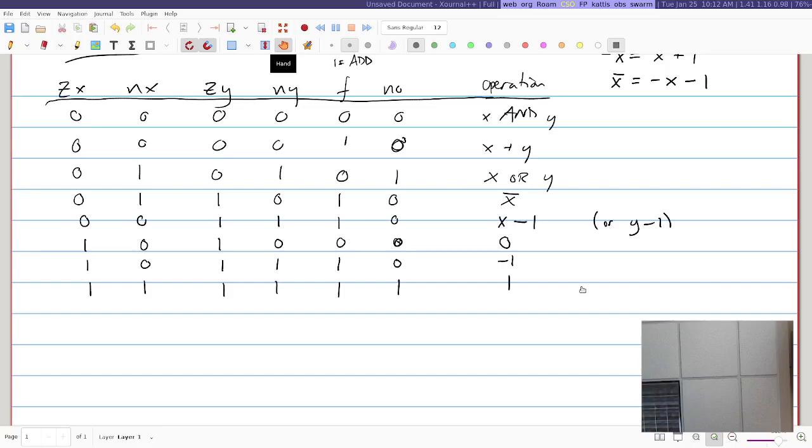Division is expensive. So if you were going to divide by 2, you'd rather not use the general division circuit, because dividing by 2 is just shifting the bits over. The computer also has a way to shift bits, and that's really fast. That would be something a compiler would do. It would notice, oh, you're dividing by 2 here, so I'm going to output the instruction that tells it to shift bits, not the division instruction. That can make a big difference, but for this ALU that we're talking about, there's no difference at all. If you can find a way to do it, that's fine.